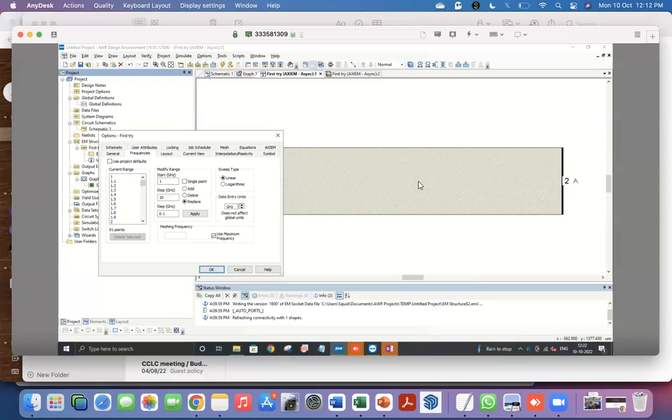This works only if your EM structure's frequency response is assumed to be a smoothly varying thing. Now, for things like transmission lines, it's usually like that. But if you simulate an EM structure which is supposed to have a very sharp resonance with very few points, then you're not going to be able to see it. So this requires some thinking about when you can do this or not. But it's very useful to actually run the simulation in a short period of time.